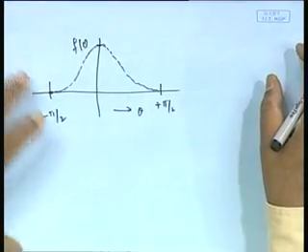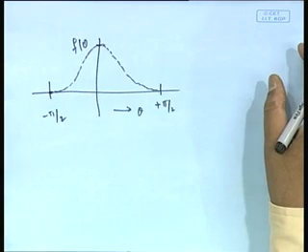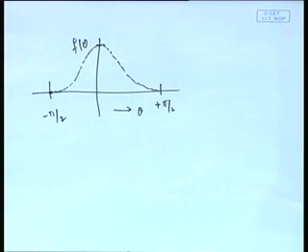People have also analyzed the spreading function somewhat by taking the wave slope. Although I say you cannot measure, you could measure nowadays with sophisticated instrumentation the slope also from a random signal. After all, if it is all going in x direction, I have a slope in one direction. If it is coming from this direction, I have slope in a different direction. So, if I measure the slope, I get a feel for the content of directional waves. Obviously it is found most waves are in the direction of the wind.